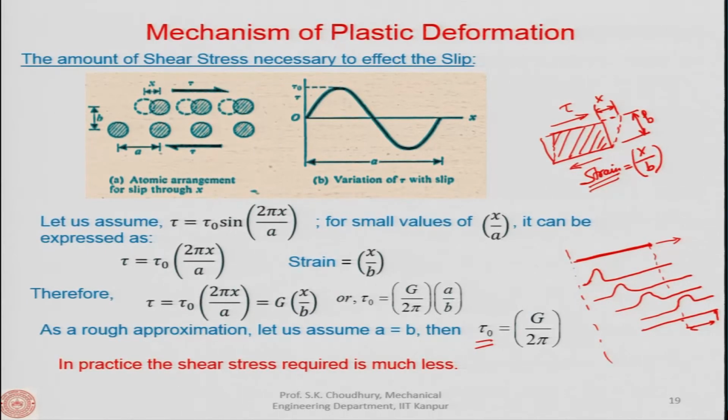As a matter of fact, we will see in one of the processes that when plastic deformation is made within a layer of almost perfect material, that is an ideal material, the forces will be very high. When forces are high, the power consumption for that process will be very high, because as I said, power is the product of force Fc and the velocity Vc.